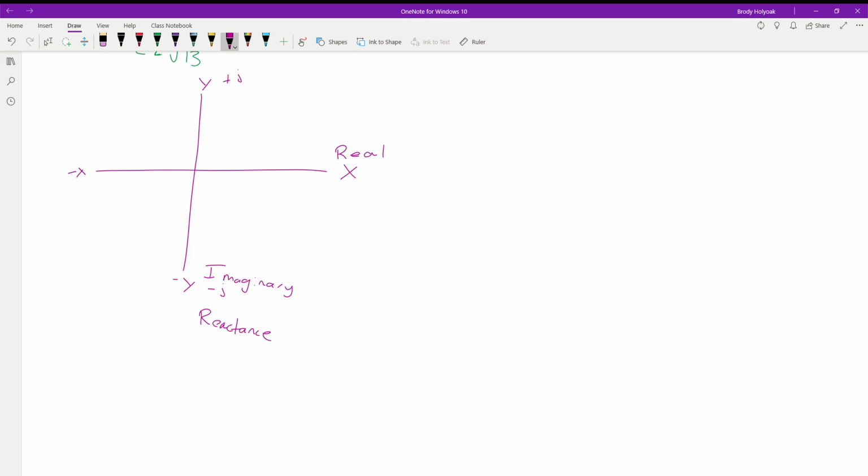Each component that we mess with, and even the ones we're doing now in lab, we're measuring across resistances. They still have an imaginary value, if you will. It just happens to be 0. So we ignore it. Inside of a resistor, there's nothing that's going to react differently between 1 megahertz, 6 megahertz, 2 millihertz. It's not going to change. So there's no reactive components in this component whatsoever. But like I said, capacitors and inductors are.